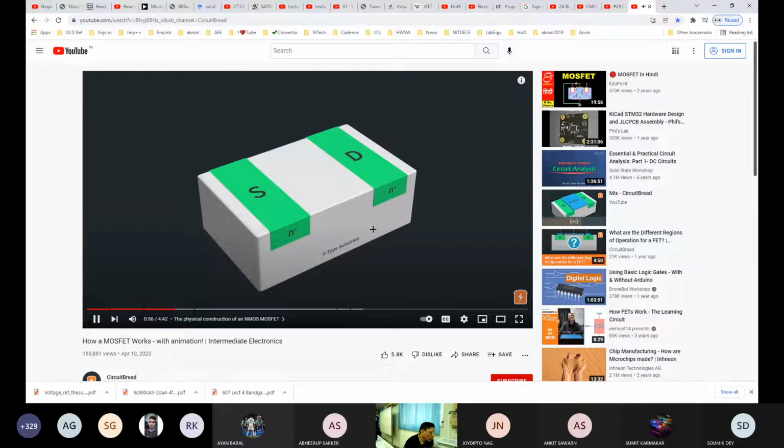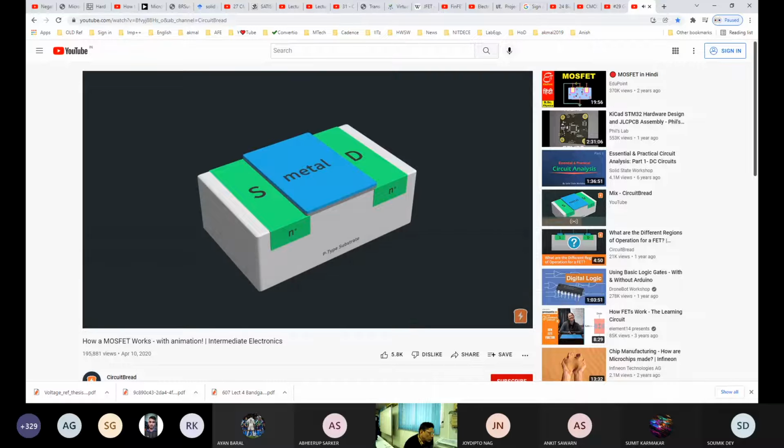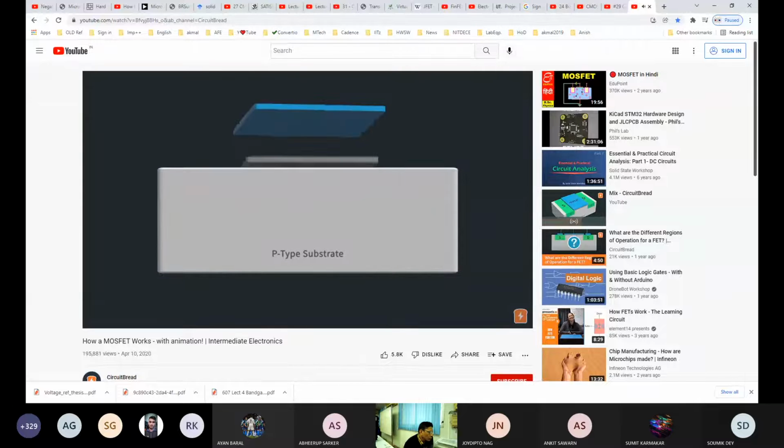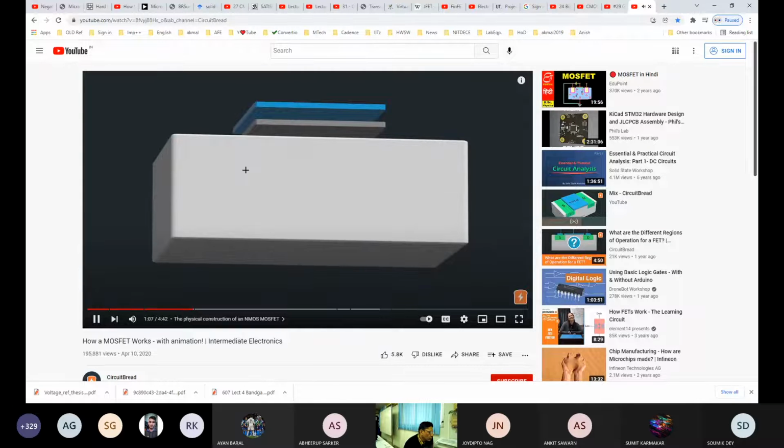On top of the substrate, an oxide, which acts as an insulator, is deposited. Then on top of that, a layer of metal is deposited, which finalizes the gate structure. Now you can see where the metal oxide semiconductor in MOSFET comes from. Although we call it metal, the modern transistors do not use a metal here, and typically heavily doped silicon is used as the conductive plate.